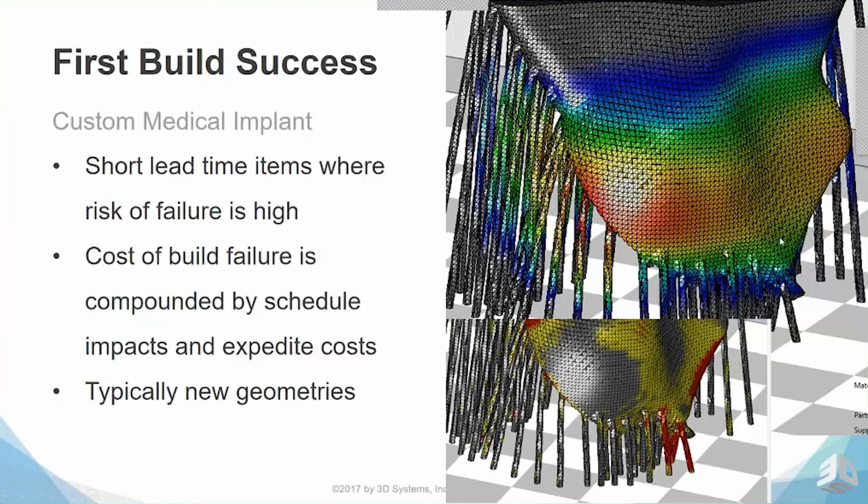And while the deformation may still look good, you see that on the bottom we do have some plastic deformation in some of these supports. So these supports are probably going to crack. Maybe it happens after the part's been building for quite some time. But you'll still see a layer shift when those parts crack because a lot of that stress is going to be released and everything's going to move just a little bit. And that's something that we definitely don't want.